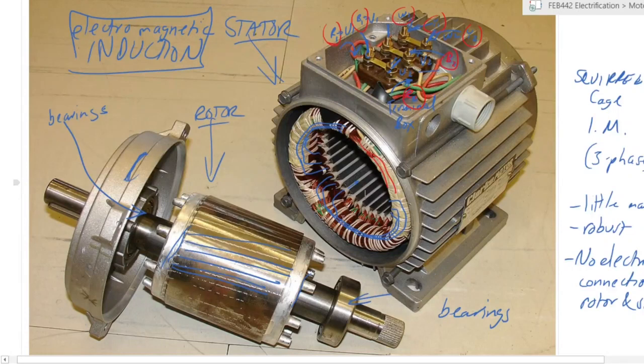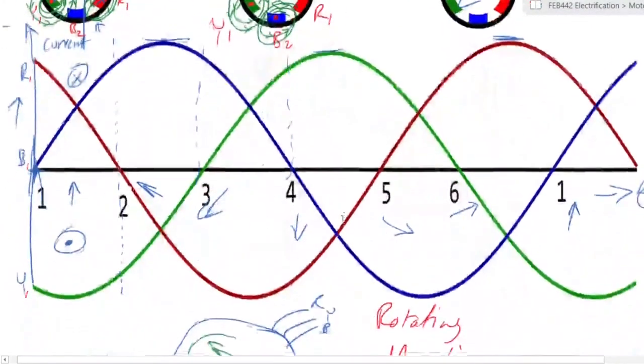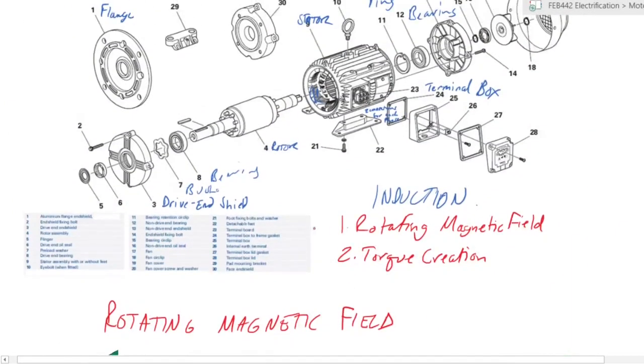Without physically moving anything, without applying any mechanical energy, you have a magnetic field that, from the perspective of the motor inside the machine, is being rotated. It's almost like you have a magnet that you are rotating, similar to what we had with the alternator, a magnet that you are rotating inside the space of the stator. So that's principle number 1 of your induction motor operations. Okay, you have your rotating magnetic field.